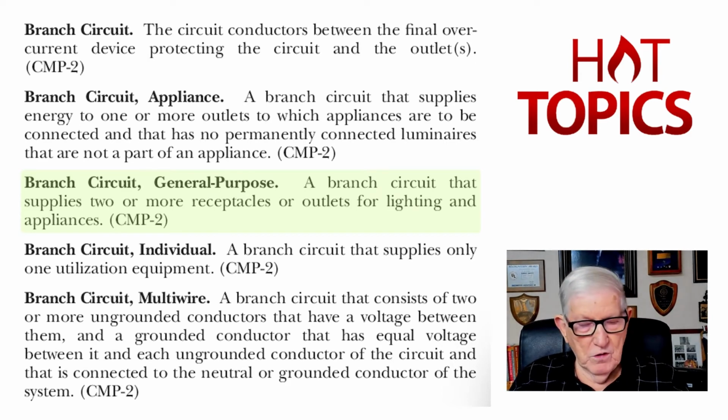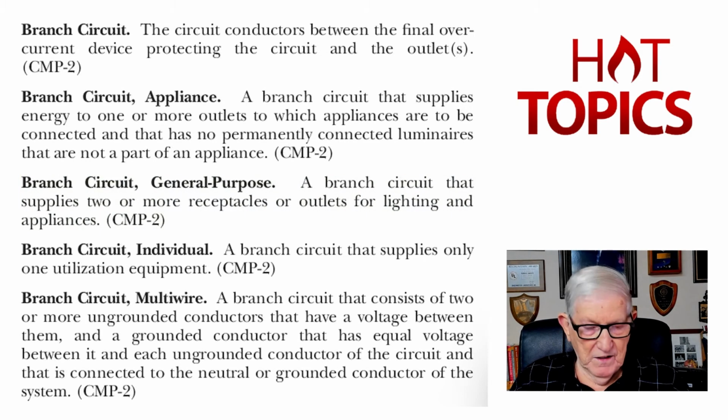And then, of course, if you want a branch circuit appliance, that's listed there. And then your branch circuit individual. Basically, if you have an individual branch circuit, then the overcurrent device matches the conductor and the cord and plug connected load. If it's an air conditioner with an inrush current that you want to hold, that load would appear in Table 240.4(G) of the code, which we'll review.